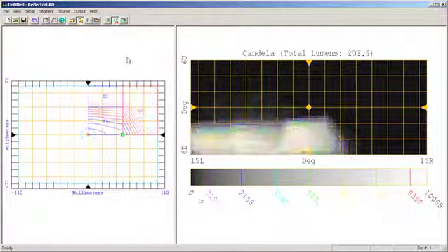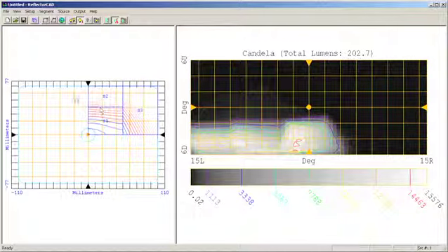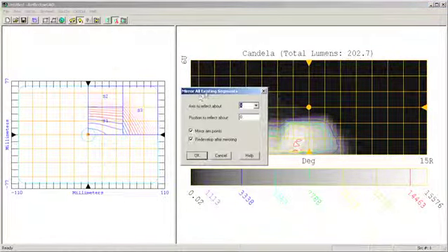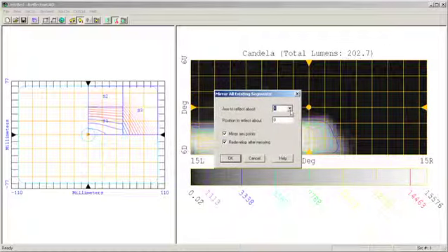Now, I could continue to design, and in doing so, put in each one of the other segments for this quadrant, as well as this quadrant in the lower right-hand corner. ReflectorCAD has an easier way of setting up these segments, however. I can come to my segment button and click on Mirror Existing Segments. I have the ability to mirror segments about the X and the Y axes.